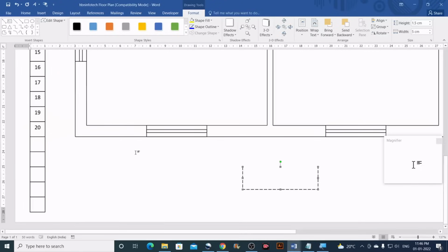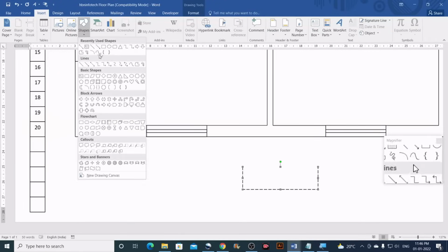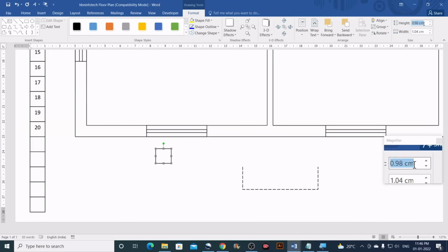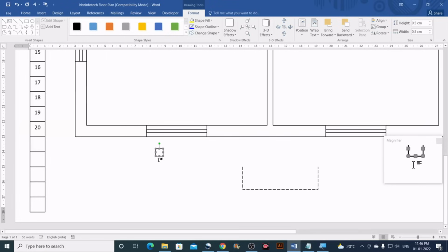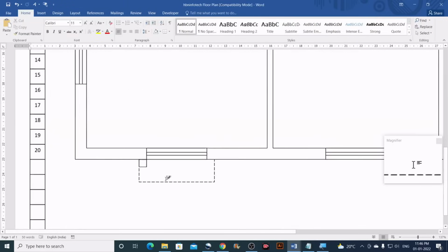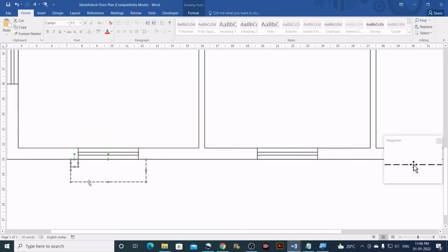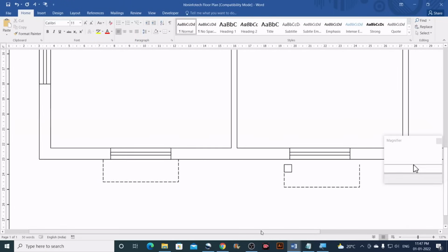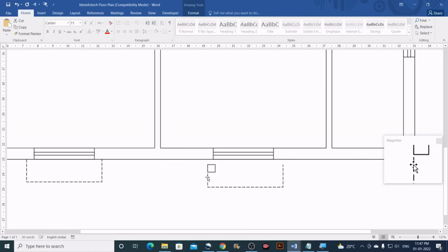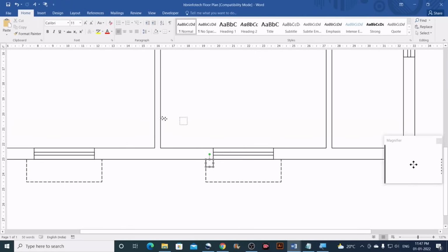So we'll roughly create a shape, a rectangle, which is 0.5 and 0.5. So we'll just keep this here and then take this one, align this here. So it's simple. We'll continue the same method. So we will need to duplicate this, select both, hold Ctrl and drag, delete this one, and I'll place this here. Now move this away.